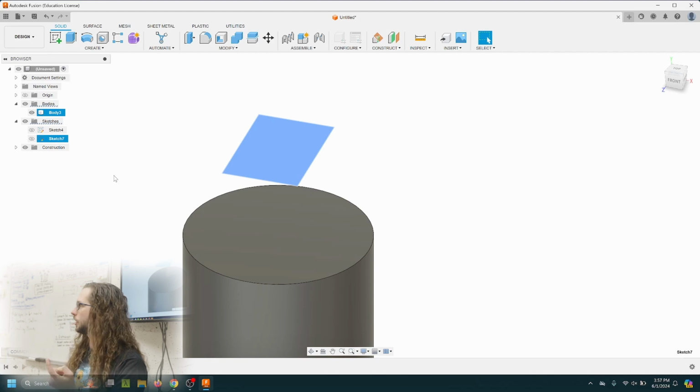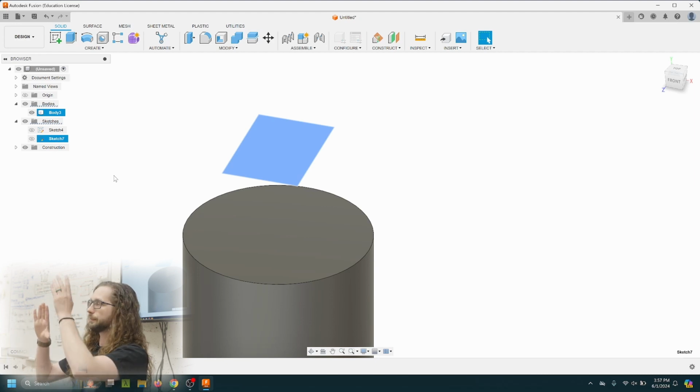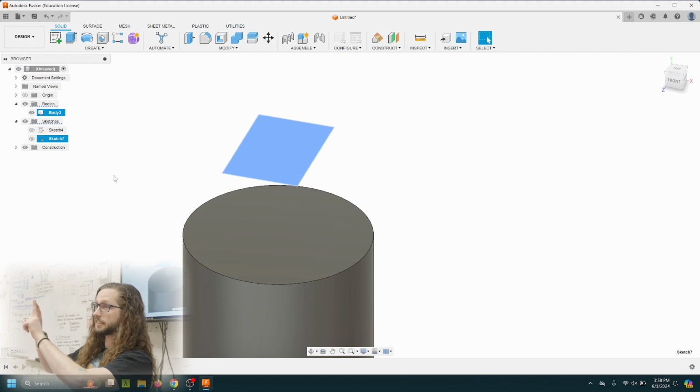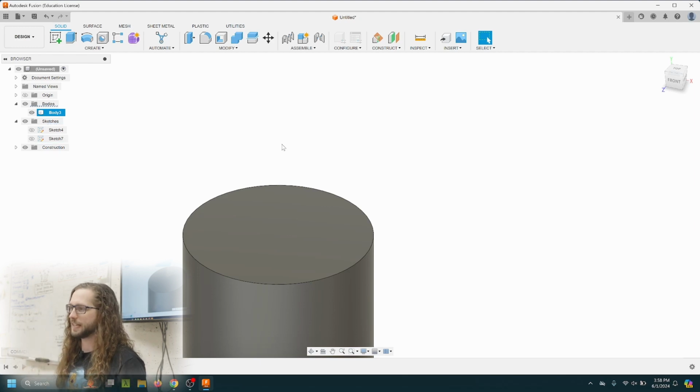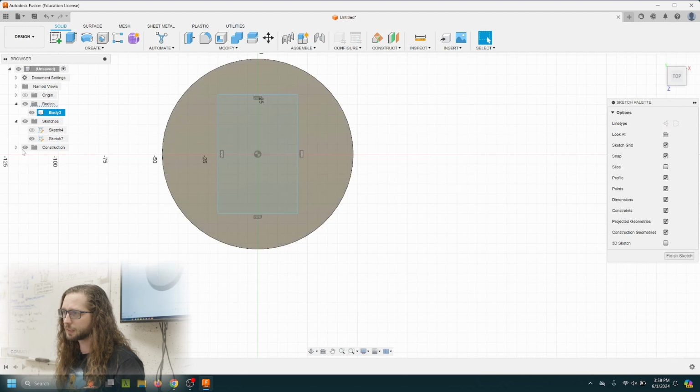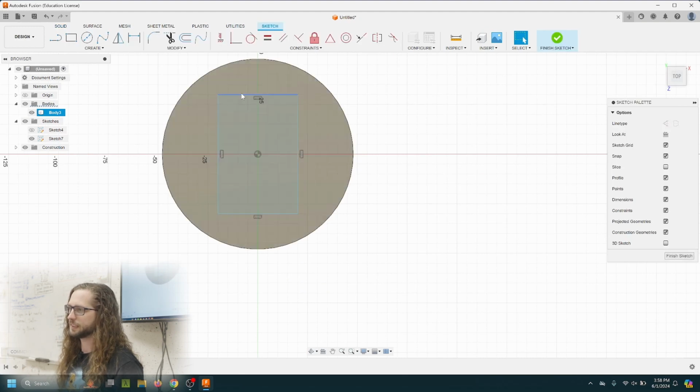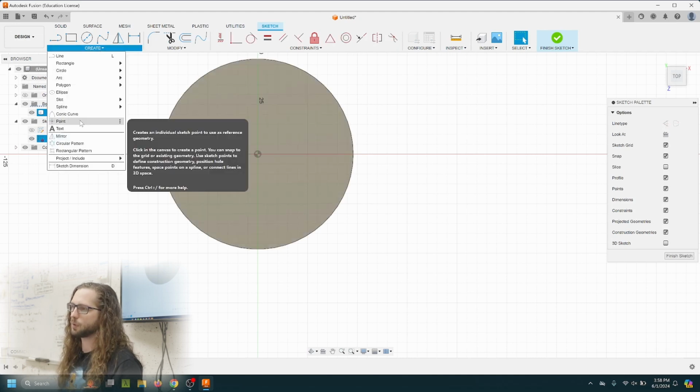I could use the revolve tool, make a slice of my dome, and then revolve it. The other thing that I could do, and I'm going to go into that sketch of the rectangle I made, is, let me delete the rectangle, is instead of revolving around a curve, I can loft to a one-dimensional point.